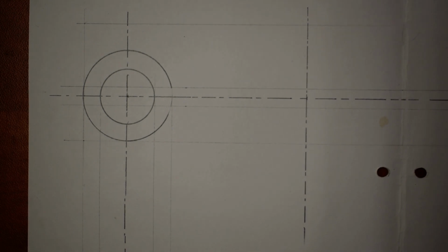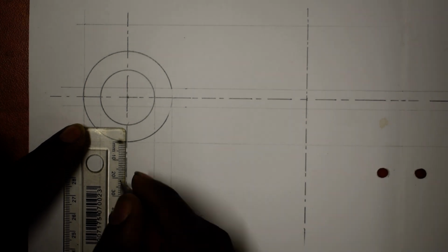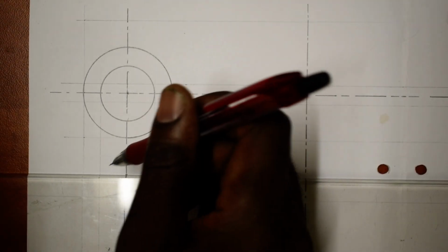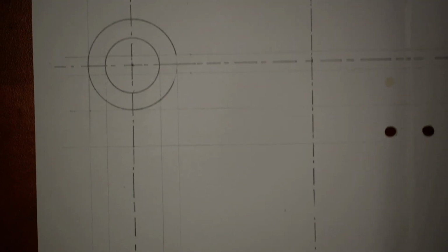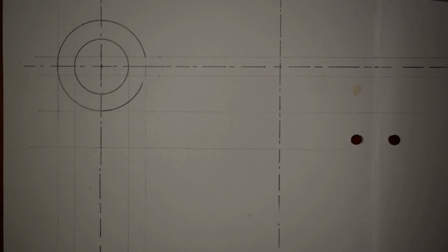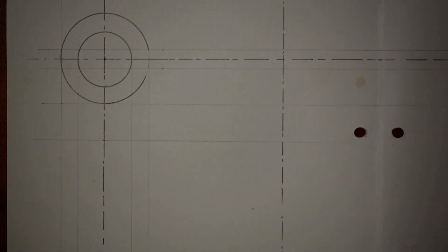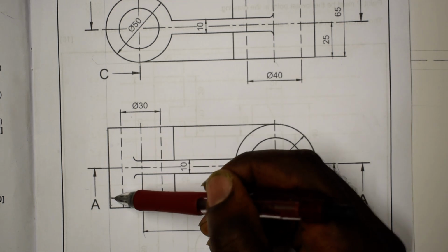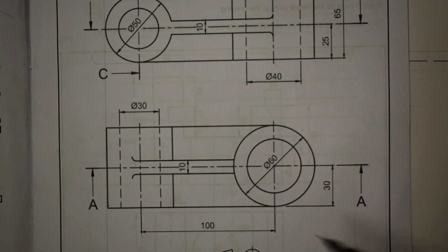Right. So now what is going to happen? From here going down, I can record 20 millimeter. There is my 20 millimeter, because we separate our views with 20 millimeter. So I draw a horizontal line. So which means beyond this 20 millimeter, everything's supposed to be recorded. You get it? Beyond this 20 millimeter, I have to record every dimension. You get it? So from there, now what is going to happen now? So from here till here is how much? From here till here is 60. You get it? It's 60 millimeter, which is the breadth.